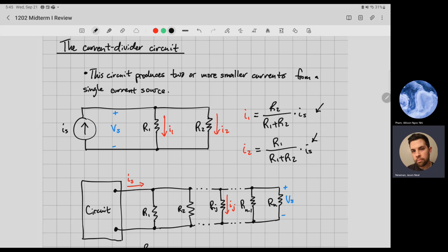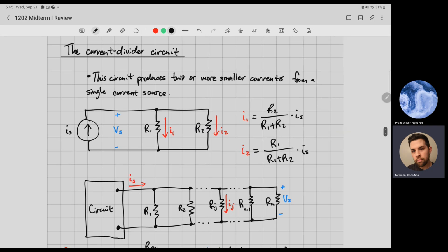There's this restatement of Ohm's law. Yep. You can just use KVL, KCL, and Ohm's law. You don't technically have to do it. Yeah, you can actually. There are videos on YouTube where it shows the derivation of these current dividers and voltage dividers. They're out there. But it is just Ohm's law essentially. Yeah, good question. And so the current divider circuit.